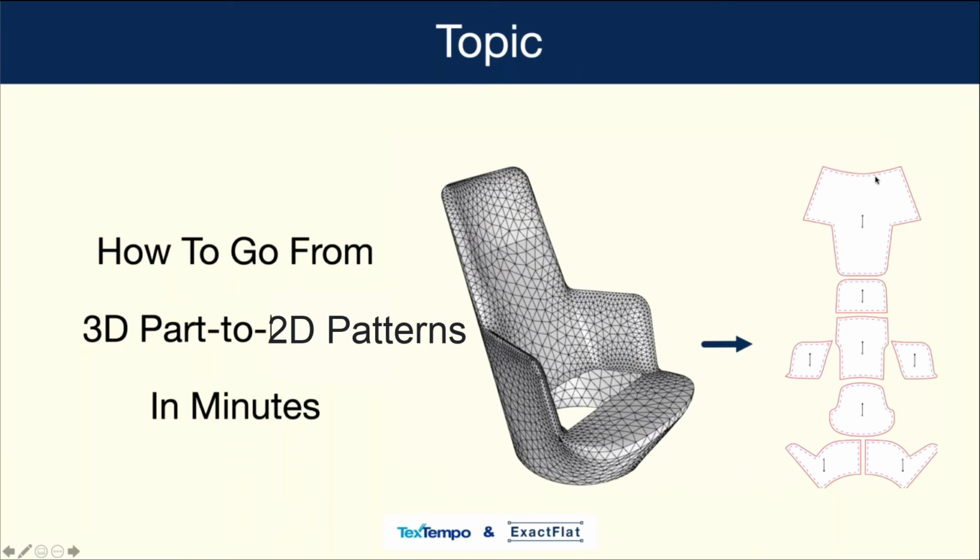So if you look at this mesh here, we have meshing tools that have more or less equilateral triangles. The change in size between the triangles is gradual, and we can adapt the size or we can keep them uniform. These meshing tools lead to better results because these are computational algorithms that have to work on the mesh, and to the extent that the mesh is predisposed to those computational algorithms, it's better.